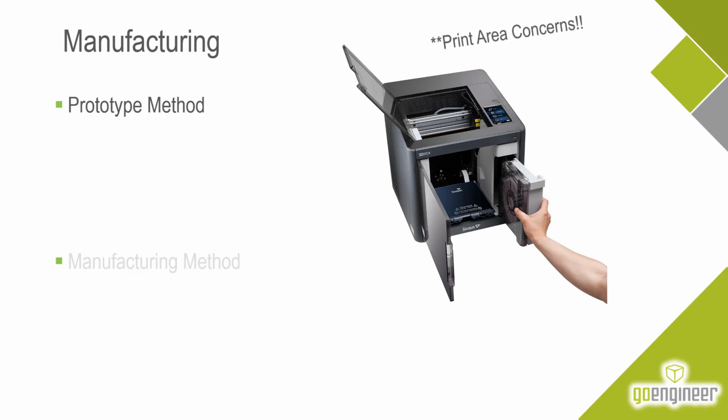Manufacturing method, well, that's something we're going to worry about later. But on the printer, one thing you always have to be concerned when you do have access is how big is that printer? What are the areas of the printer? So the volume of the print is going to really constrain us into whether we can make our part in one piece or whether it's going to take us a multiple split in order to fuse these together later. But again, methods are all available to really pull each of these off.